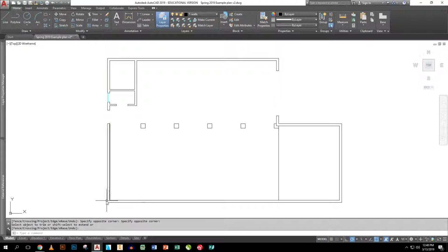Now over here, I have 3 windows and then a door and then a set of windows down this wall. Now, I'm going to come back and put in the 3 windows as space provides. But first off, I'm going to offset approximately 9 feet. In fact, not approximately, exactly 9 feet from here over. That line, I'm just going to go in here and break it. So BR for break, and then I pick where I want to break it back to, and then just get rid of this piece back here that I don't need.